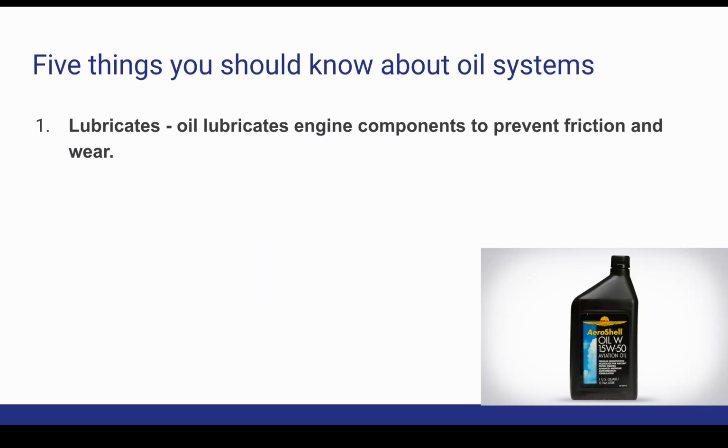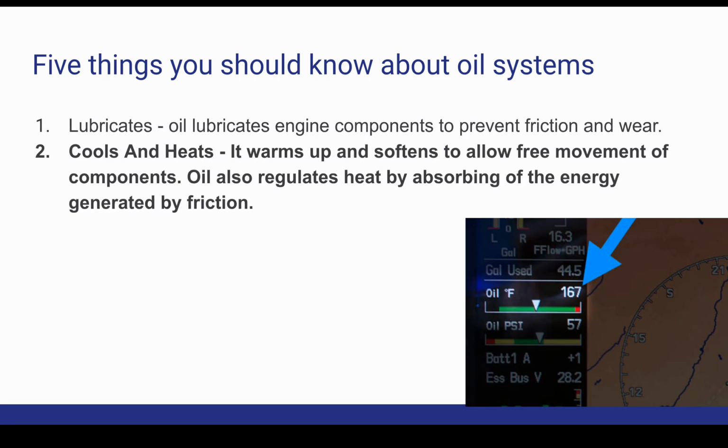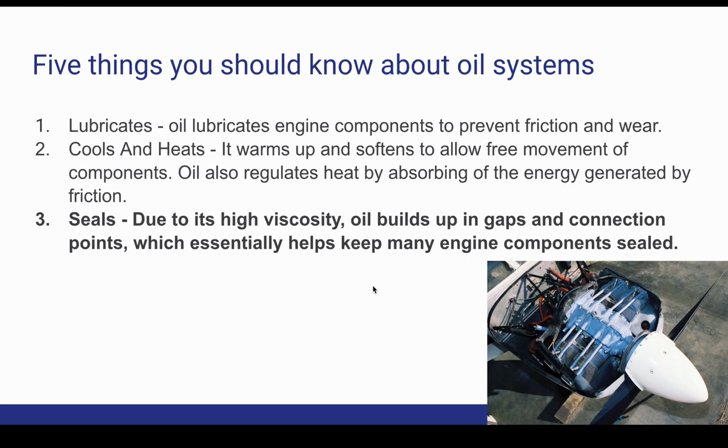It lubricates, is the first thing that oil does. You should know it cools and heats both. It warms up and softens to allow the free movement of components, but it also regulates heat by absorbing the energy of generated friction. There's a little oil gauge there. That's a digital one. It seals.